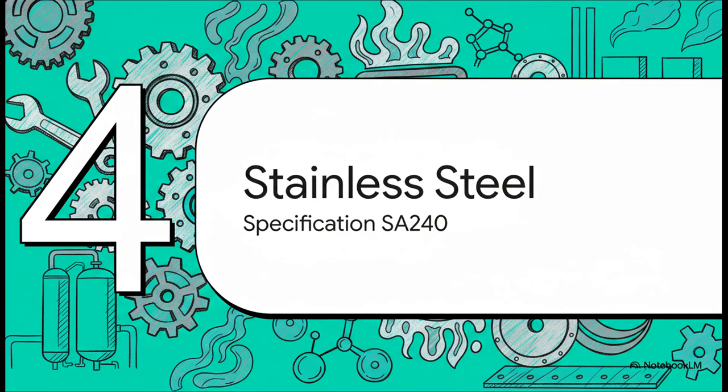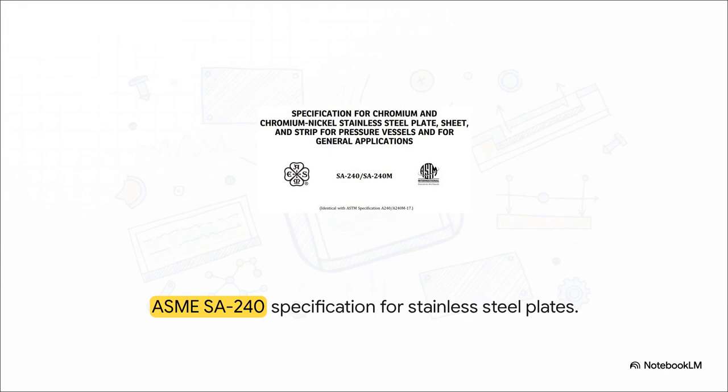Section 4. Stainless steel. Specification SA 240. But hey, what happens when carbon steel simply won't survive the job? Well, we transition to the other main base ingredient in our EPC kitchen. Just like carbon steel, stainless steel has its own dedicated, highly specific rulebook. SA 240 is the exact ASME code section you absolutely must turn to when your project requires chromium and chromium nickel stainless steel plates. You reach for this specification when you're dealing with highly corrosive fluids, strict hygiene requirements, or operational conditions where standard carbon steel would rapidly rust away and just completely fail.